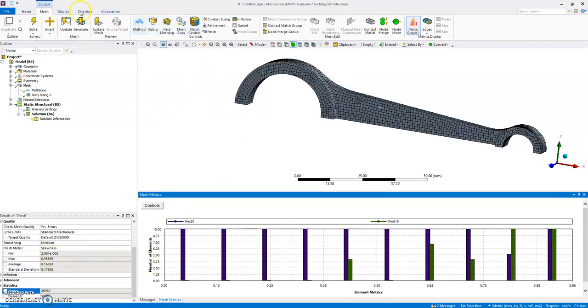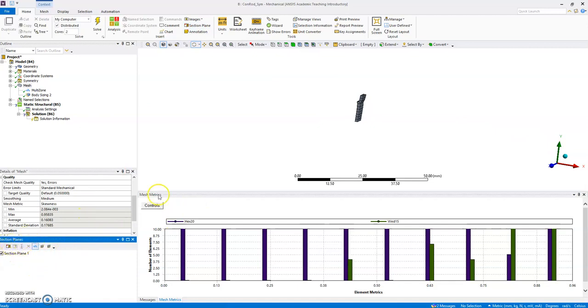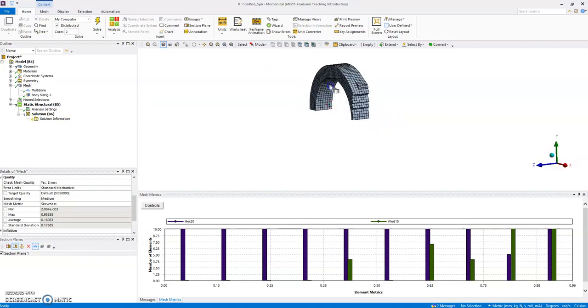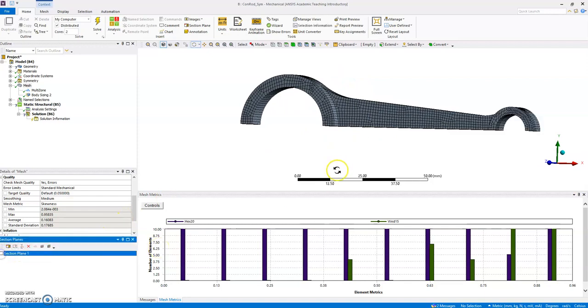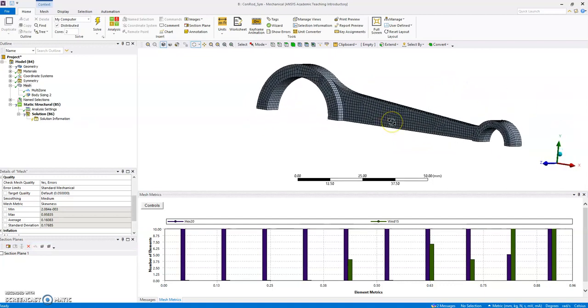Let's have a look through the section plane. Let's select it. Now I want to see everything. That one, dynamic. Oops. Need to select it first. Apologies. Yes, that's quality mesh in general. Most of it is quality, with some issues near the tip of that fillet. So the point is I need to simulate it, and then maybe make some more decisions based on the result of the simulation. To simulate, I need to add some loads beforehand, and I will do it in the next video.